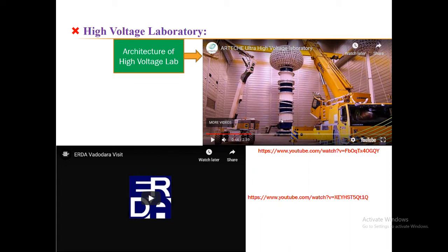Yes, this shows the three-stage cascade transformer, and over the top the high voltage electrode is generally electrostatically shielded. Shielding is very important when you are working with high voltages, just to avoid the surrounding air becoming ionized.